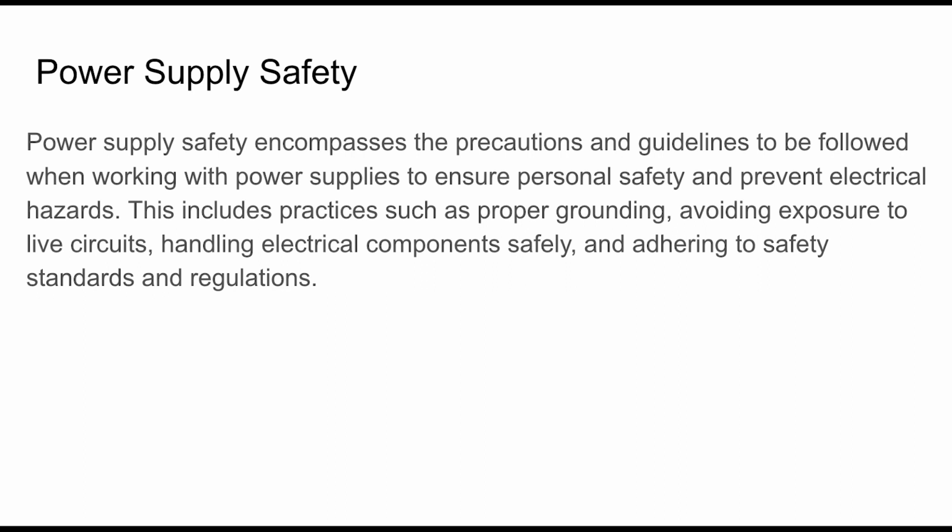So a lot of other power supply safety and just computer safety in general, make sure that your circuits are not exposed, make sure your motherboard isn't exposed, make sure it's not getting dusty because it can catch on fire, make sure that there's no foam or plastic, like thin plastic that carries static. Make sure that you're not carrying any static because static can fry memory. So just make sure that you're using common sense practices when it comes to operating and maintaining computers and working on any of this hardware.